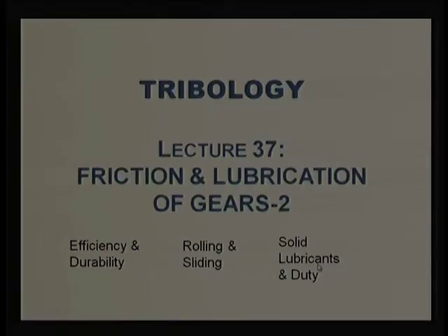For medium and heavy duty load applications, we will not be able to utilize polymers. Polymeric materials are suitable only for light duty applications. For heavy duty, we need to use some sort of liquid or semi-solid lubricants. Solid lubricant coating can be done, but it will wash out and we need to replenish it one way or another.